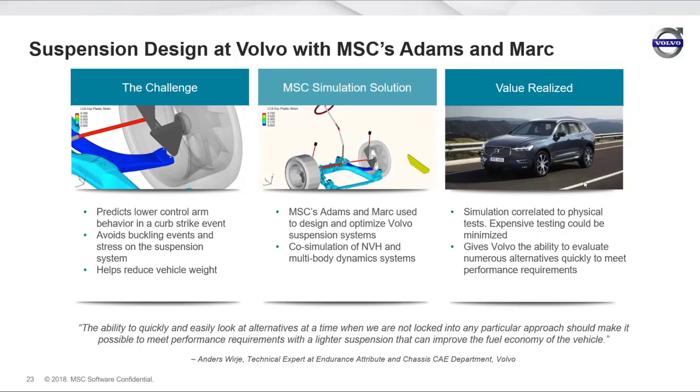As the wheel goes over some fairly aggressive lumps and bumps, with curb strike in particular, that's going to have an impact on a good chunk of the car. So here we can start to understand what sort of loads are getting transferred where and how, and we can start to simulate buckling events and stresses and strains on the suspension systems within that.